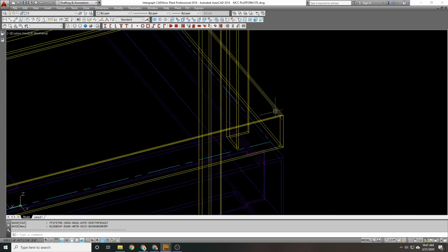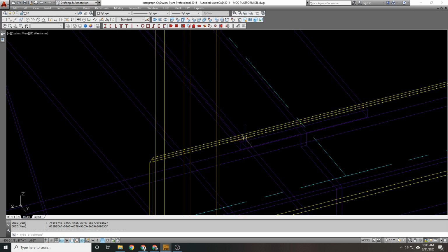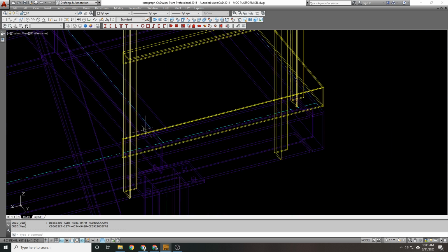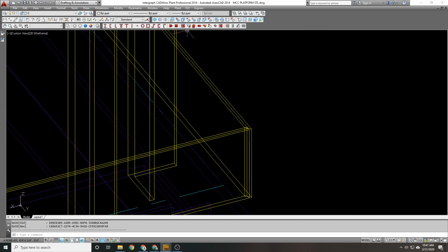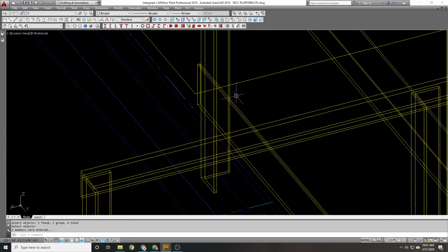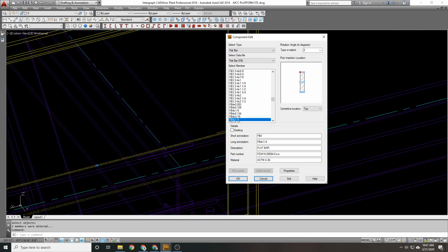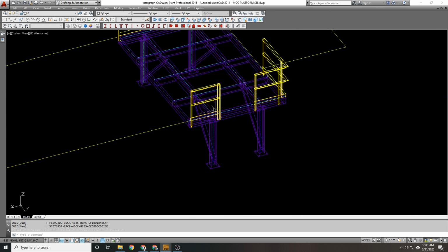There we go. And this thing mitered but kept its kind of goofy overhang as well. So back to 1/4 inch you go. And it got rid of the miter, which, you don't have to have a miter for these, but I do. All right, that's it. Let me get rid of this one. There's our handrail. I'm not gonna do the stairs in this video.